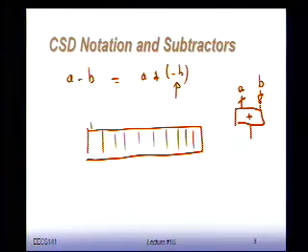Can you use carry in maybe? Sorry? Carry in? The carry in, that's exactly right. Remember this adder? There's always 3 bits, A, B, carry in. Now for the first bit, the least ordered bit, we always connect the carry in to 0 because there's nothing coming in from the previous word. But if I now would connect this just to 1, I can turn this into something that subtracts very nicely.